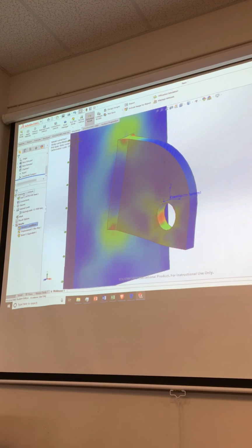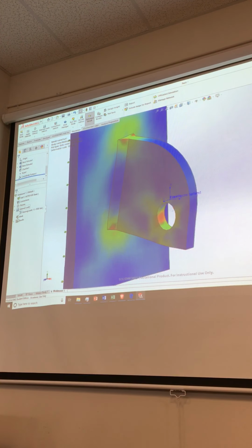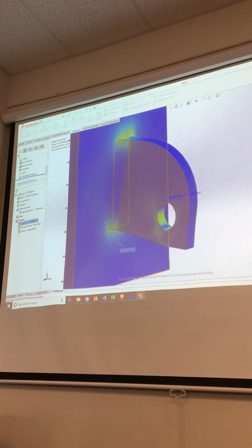What do we do? We turn on the adaptive stuff, right? We go to the properties. We go, hey, we're going to H adaptive. We'll crank it up. We'll give you lots. We'll go through 5 times. I won't even coarsen the mesh here. So I'll say okay there. Let's see what the mesh looks like to begin with, just so we can get detail. I start with 2,500 nodes, right? It's where I am right now. We can go ahead and run this. It goes through in chugs. 2, 3, 4.